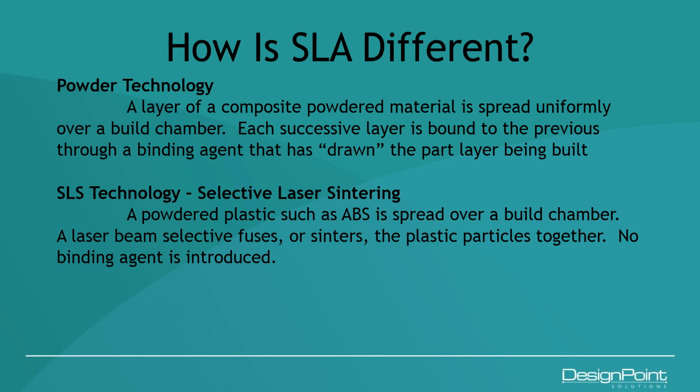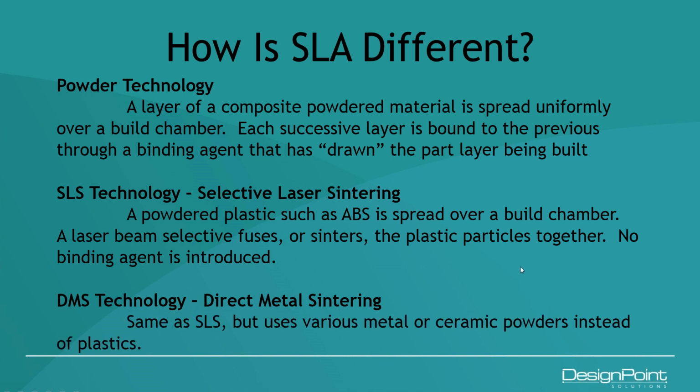Along the line of powder technology, we have DMS technology, which is known as direct metal sintering, and this is basically the same as SLS, very similar to the powder technology, but instead of using a plastic or a gypsum-based medium, it uses various metals or ceramic powders instead of plastics.